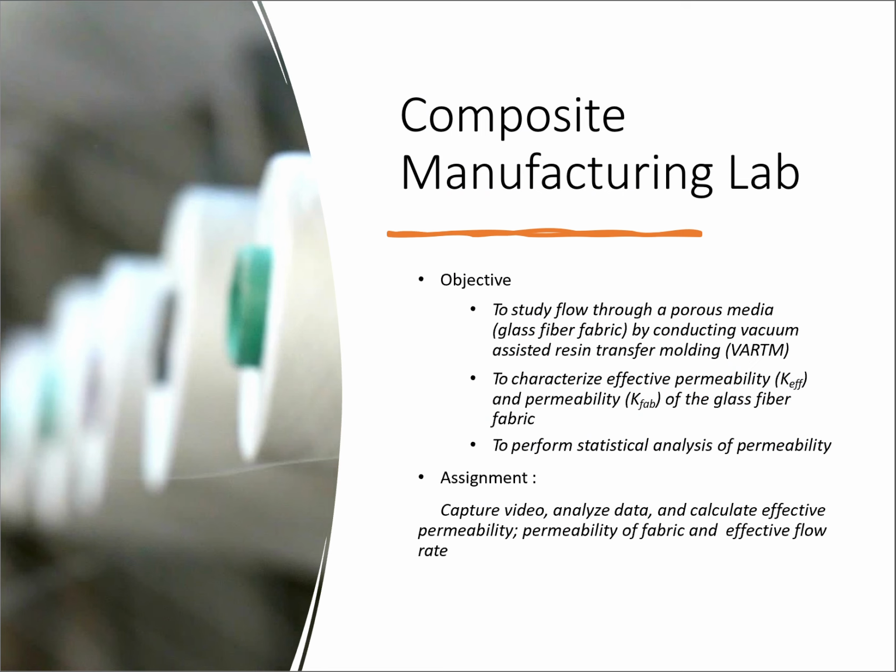The objective of this lab is to study the flow through a porous media, which is essentially just a glass fiber fabric, and the fluid that is moving through this porous media is the resin. Then we are going to learn how to actually build a composite plate using the VARTM method. Your goal is to characterize the effective permeability of the glass fiber fabric, and eventually you have to do a statistical analysis on the permeability of this fabric.